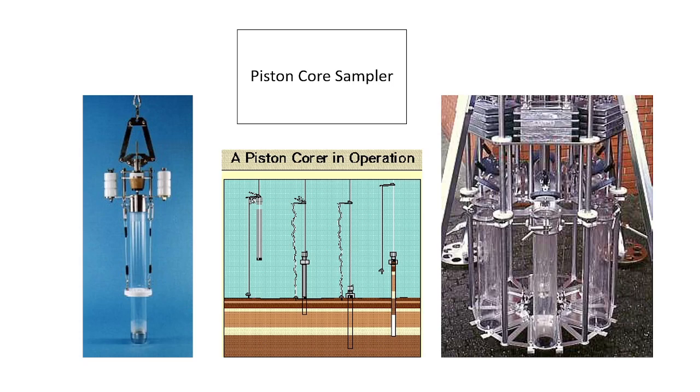First we penetrate the sampling tube, and now the sample is in the tube. Now the piston creates a suction pressure, and because of that the sample will stay intact and will not fall off. So it will retain the sample in the core, and this way full core recovery with minimal disturbance is possible without withdrawing to the surface.